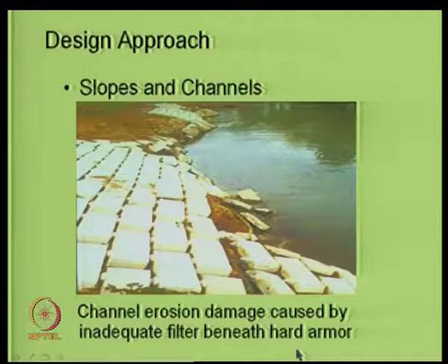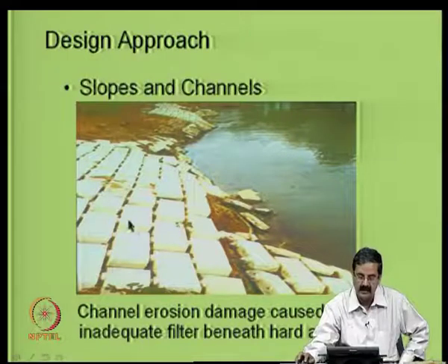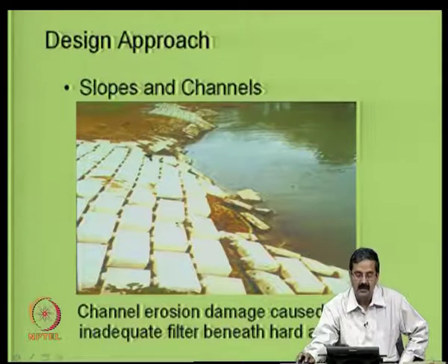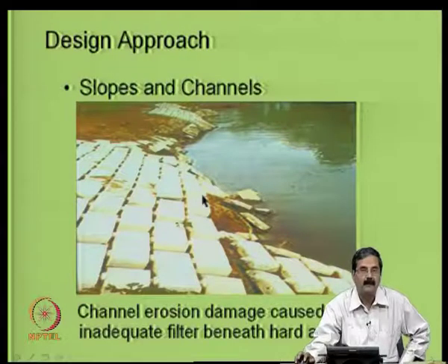So this is an example where the channel erosion damage was there because of inadequate filtration beneath the area. You can see that all these materials have gone out through this. So, if the design is not perfect, all these things are possible.